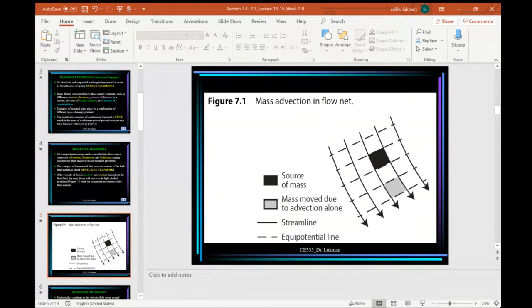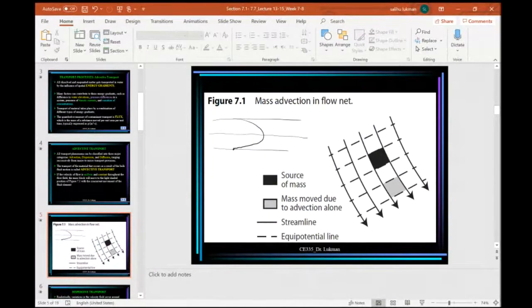Of course, we know that even for laminar flow there is still some variation. You still don't have a uniform flow per se. You still have small variation due to some other factors. If you remember, we considered this in fluid mechanics, let's say pipe flow. There is the velocity gradient. It is maximum in the middle and zero at the boundary because of shear stress, because of the fluid viscosity. So it reduces at the boundary, and it is maximum in the middle.